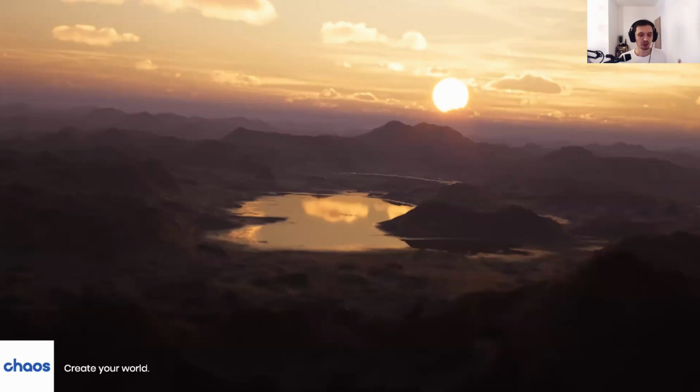So in a nutshell, we don't want to go into too much detail here because it is a complex topic, but we do support the ACES CG workflow. If you're working in a studio environment, you'll be happy to know that now you can use ACES CG rendering primaries instead of sRGB ones, if that's important to you. You can also set your bitmaps to come in the ACES CG color space instead of the sRGB one. And obviously, as it was the case in the previous V-Ray versions, we also support the OCIO workflow. Okay, so all of that is now in place, and you can do your ACES magic there, right?